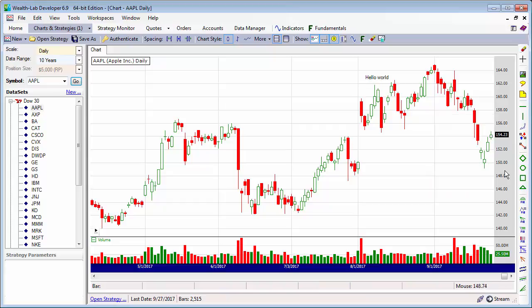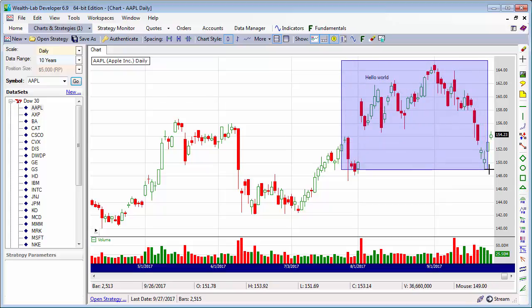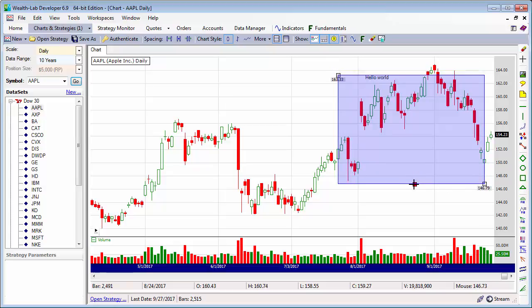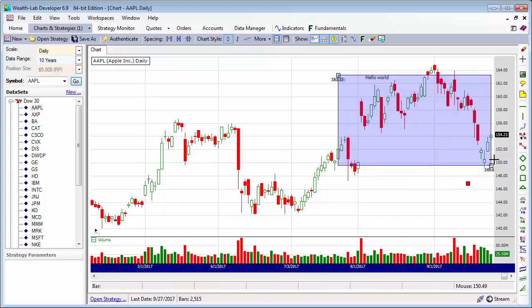To start, click on the tool that you want to use, find a point on the chart, click, drag, and release at another point. Hover over an edge of the drawing object to show the red move handles and the hollow shape handles. The move handle generally pops up under the cursor when you select an object, so it might take a few tries to grab the shape handle. The technique is to show the handles and slide over to the reshape handles.